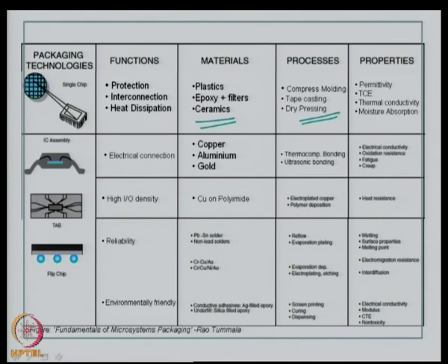There are different solder materials that we have seen, lead based, lead free, and then at the first level you have chromium, copper, gold, nickel being used. Then a lot of conductive adhesives we have seen are used today that are environmentally friendly.